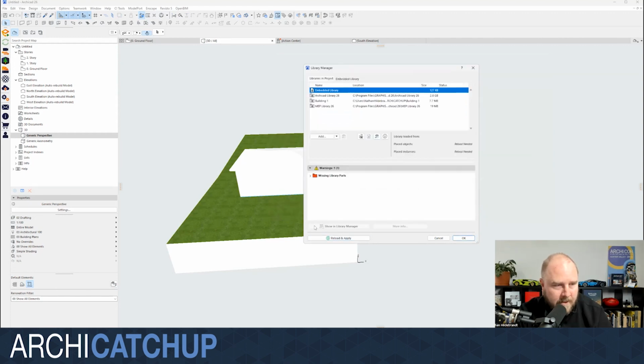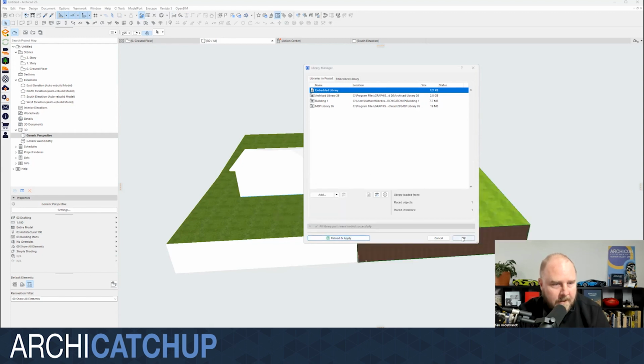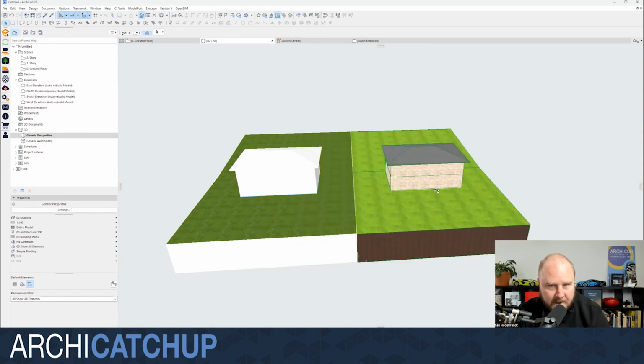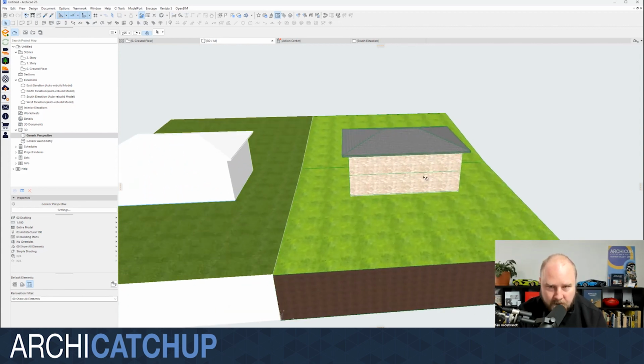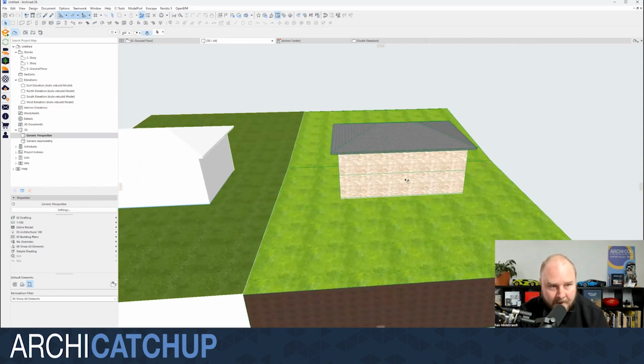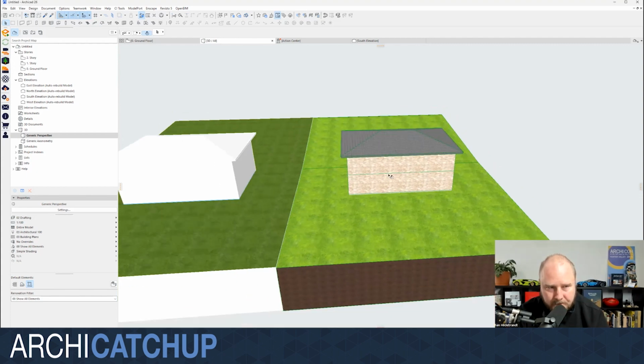And you can see here at the moment, there's warnings. So let's reapply that. And now we see it's come back with all of the textures. So the only trick to this, and the only stumbling block to this, is making sure that your naming conventions for your textures are consistent. Because if you have two Rock 01s, for example, and they're different, then there'll be conflict.